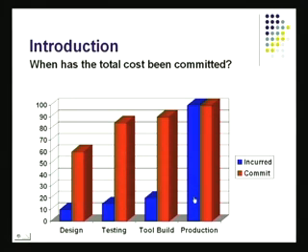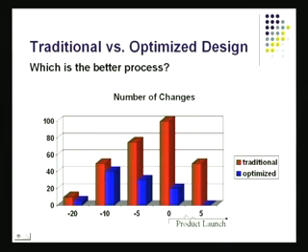If you could take care of this early on, in fact, if you could reduce your commitment, it turns out it's far better to approach the total task in the DFM way than having to do it when, for example, production begins. You look at two approaches to optimize the design. One is, of course, the traditional approach, which means you let things go till they reach manufacturing. And when the project is launched, then you really try to optimize the design, optimize the parts, optimize materials, optimize manufacturing methods, and so on. That's going to be rather late. It's also going to cost you more.